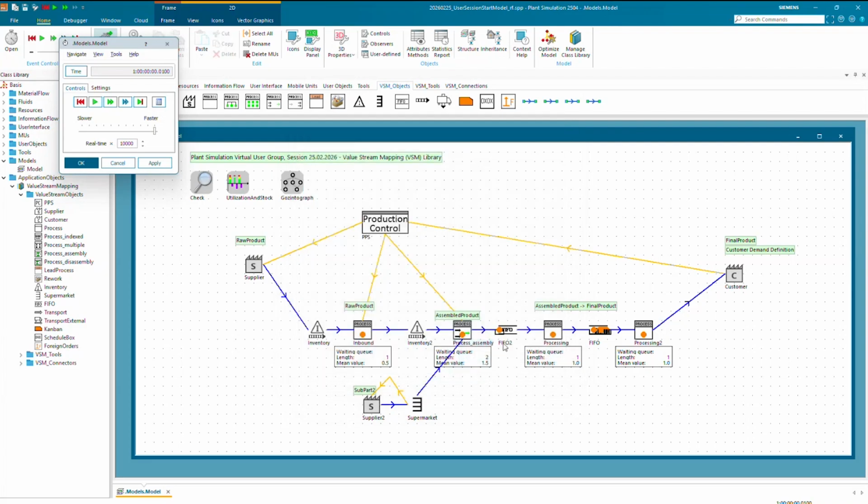Yeah, so in general, Plant Simulation has interfaces to draw data from a database or something like this. It just depends what data you might be using. So we often have discussions about cycle times or failure rates. Automatically drawing from a database, this normally is an issue of how you have aggregated your value streams, because value stream mapping is a manual mapping process. So you would define a certain station as one object with a failure rate and a cycle time, and maybe in the data available from providers, this might be 3 database lines, and then there could be an aggregation issue.